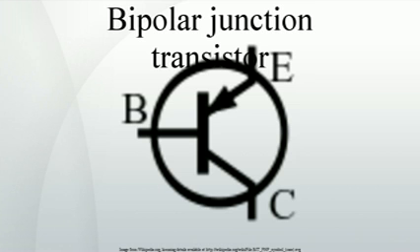Early manufacturing techniques. Various methods of manufacturing bipolar transistors were developed. Bipolar transistors. Point contact transistor, first transistor ever constructed, December 1947, a bipolar transistor, limited commercial use due to high cost and noise. Tetrode point contact transistor having two emitters. It became obsolete in the middle 1950s.